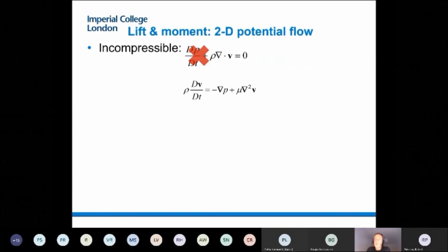Typically, this is referred to as the tip speed ratio. For wind turbines, that maximum speed is kept to around 0.3 Mach, max 0.3, which is the lower end of incompressible assumptions. And this is effectively a design choice. It's easier to design wind turbines under those conditions, so they perform under incompressible flow conditions. Incompressible means density is constant, and density constant means the first equation becomes the divergence of velocity equal to 0, which is an algebraic equation as opposed to a differential equation. It changes the essence of the problem to solve.